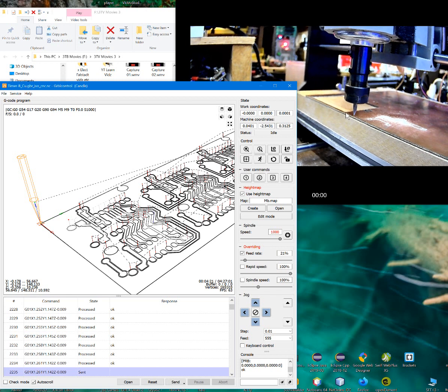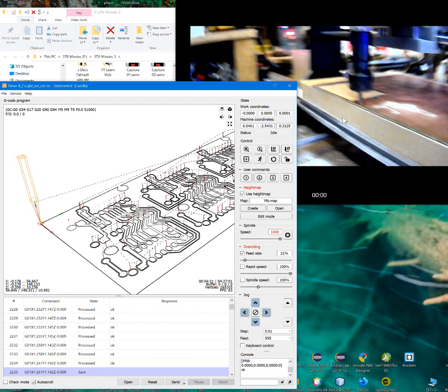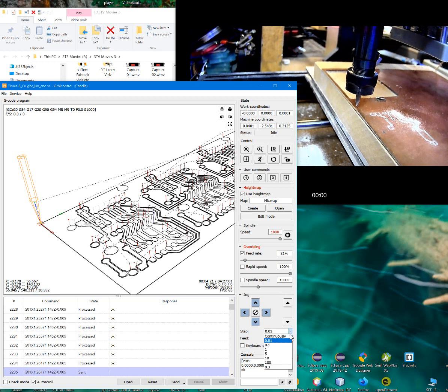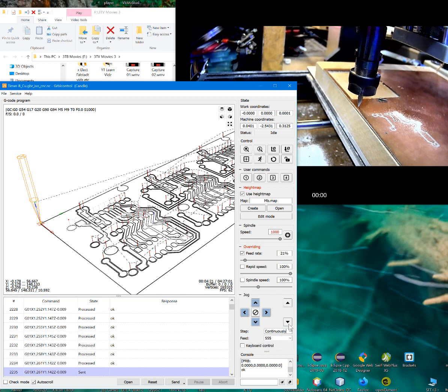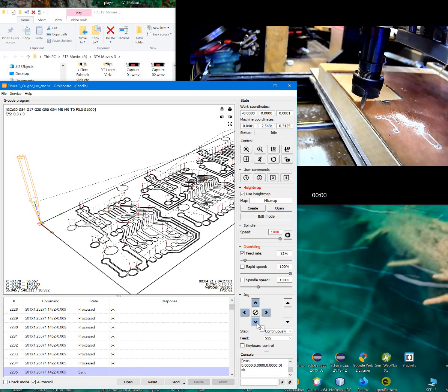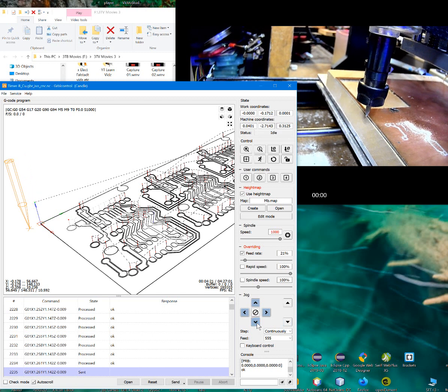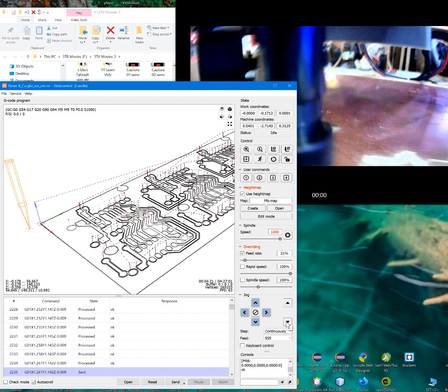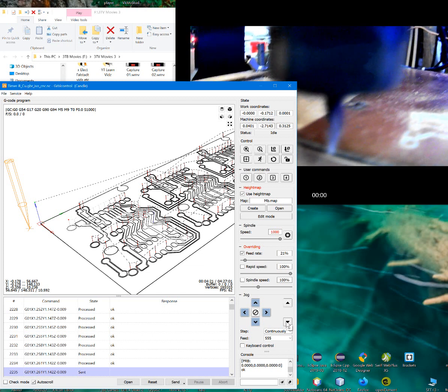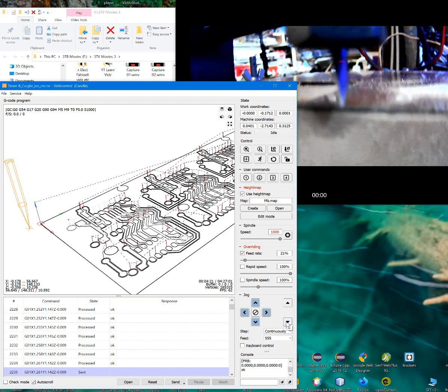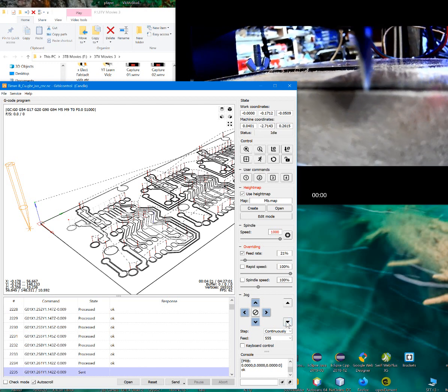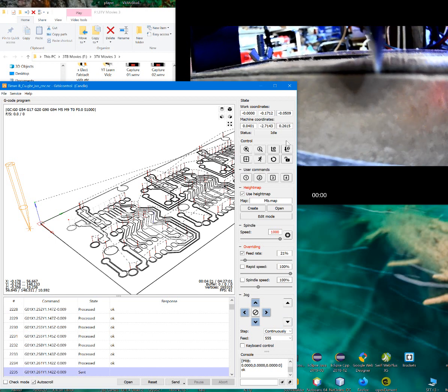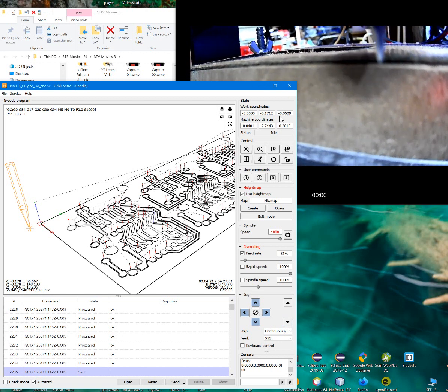Now, if I were wanting to go lower, I would actually have to take the machine literally off the edge of the board and do it, because then I can lower it below where it was. See the negative value, it's negative 5 mil, but then I could zero it here if I wanted to cut deeper.